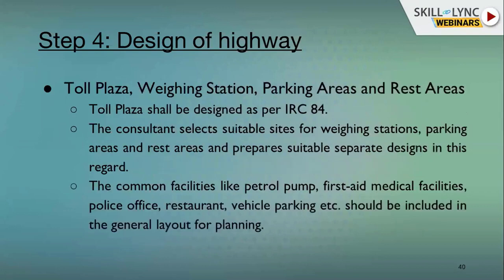In addition to that, nowadays designs include toll plaza, weighing station, parking areas, rest areas. For toll plazas, there is Indian Roads Congress Code 84. At every 50 kilometers, we need to put a weighing station, parking area, and rest area, or we have to put petrol pumps, first aid, medical areas. All those facilities are provided. These are now more or less mandatory for highway projects, and the designer needs to concentrate and find places for them during his design operation.